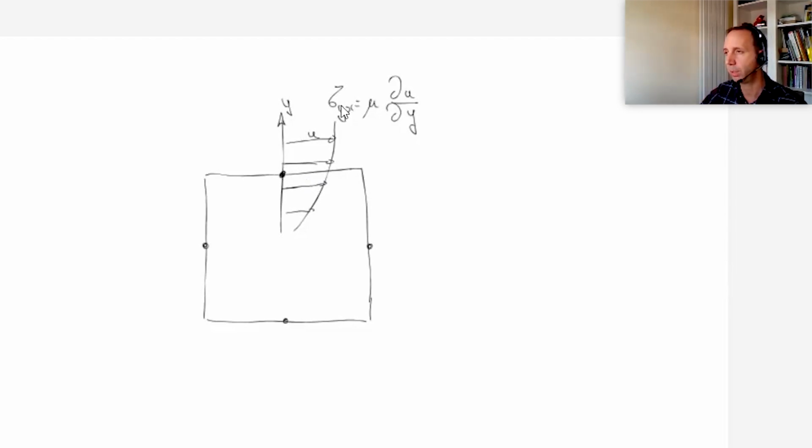The way you read it, it means in the direction perpendicular to y, and in that case, in the direction x. If you have the third direction, you could be perpendicular to y, but in the direction perpendicular to the plane that we see here. So that's the way you read that notation. For this particular problem, where you have fluid flowing only in the x direction, and that velocity in the x direction varying in the y direction, the shear stress felt right here would be equal to the value of that gradient right here multiplied by the dynamic viscosity of your fluid.